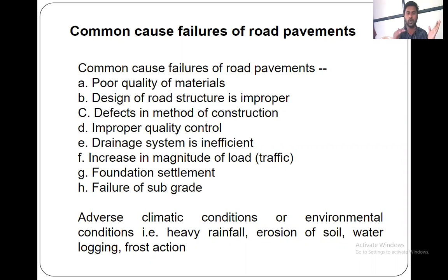If the temperature lowers, whatever water is there between the layers will get frozen. Due to this freezing action, the volume will increase, and due to this increase in volume, cracks may appear on the pavement.